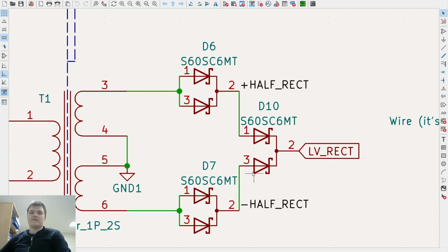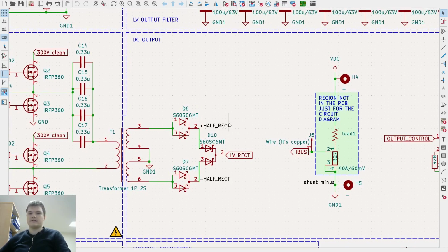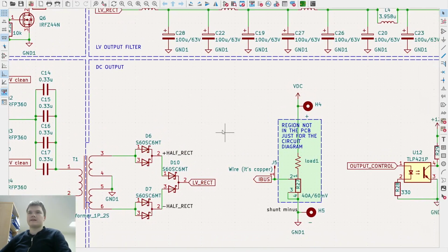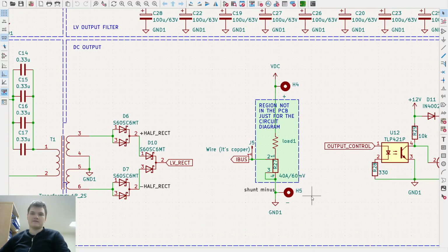They have similar voltage drops to the ones I used previously, so that significantly increases the efficiency, since now it's 2 voltage drops instead of 3 voltage drops, which is drastically, like around 10%, maybe 5. I didn't make any precise calculations regarding this change yet.